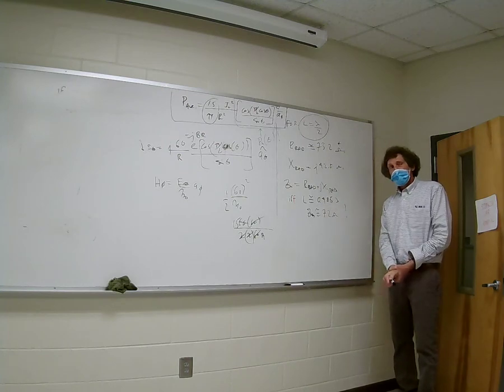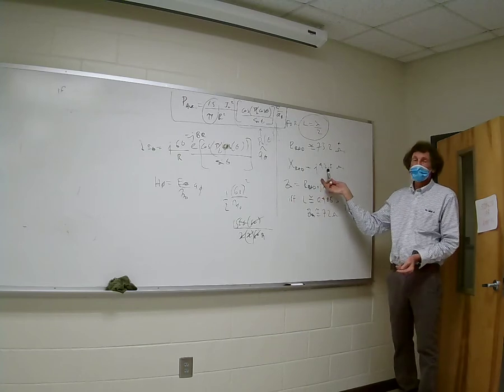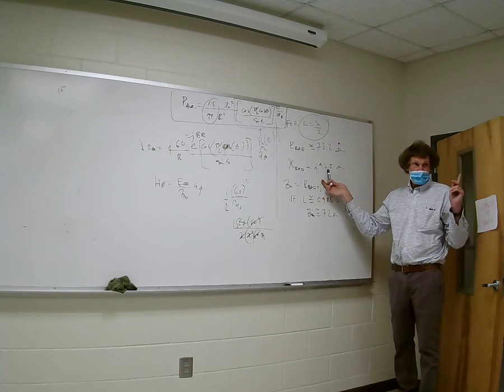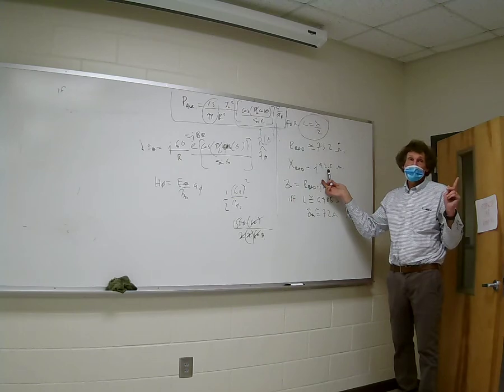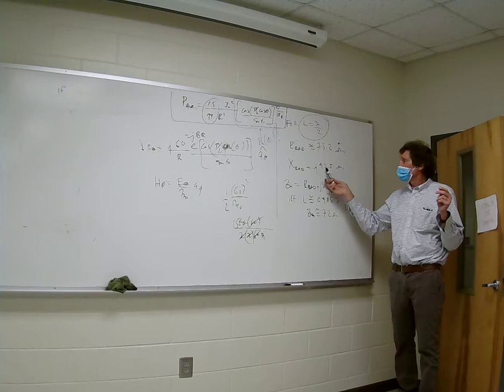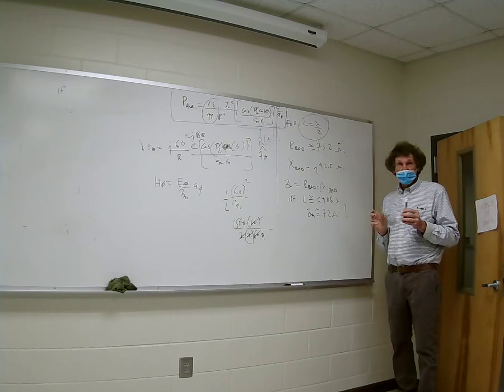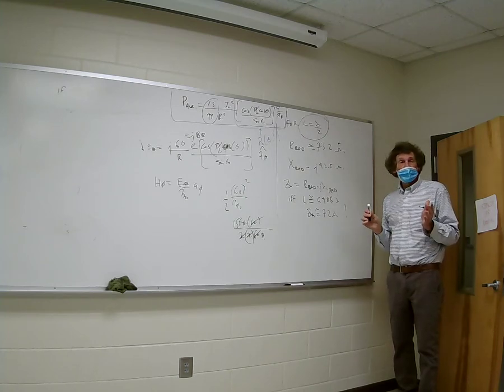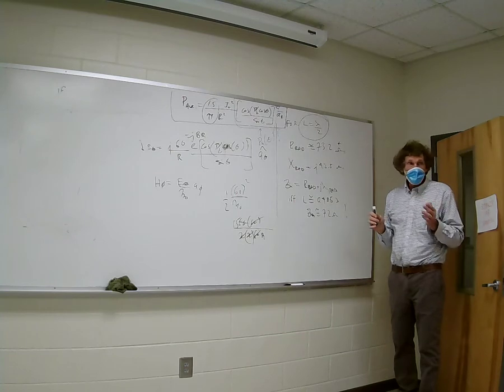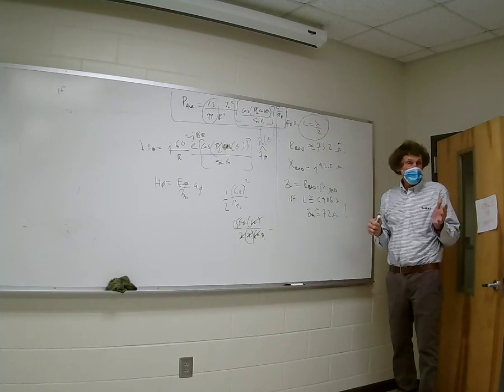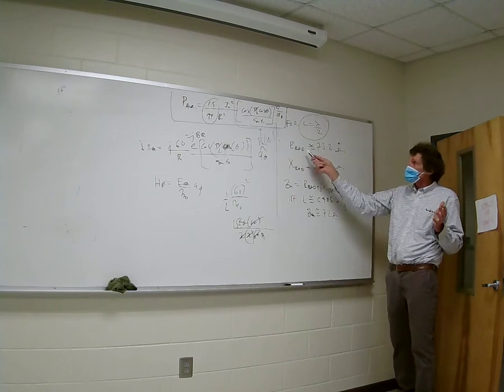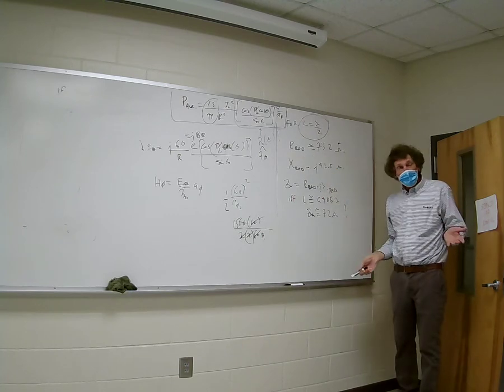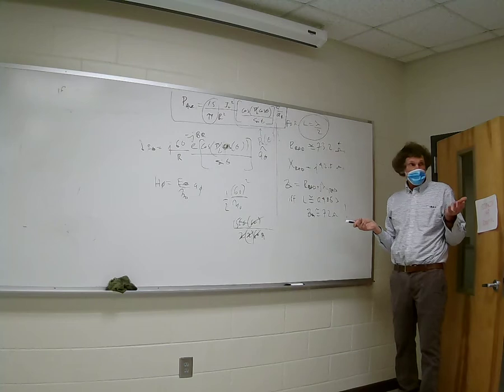The reason they do is you get rid of the reactance. See that j42.5 there? If it's exactly a half-wave dipole, you're going to have a reactance also. So you're going to have 73.2 plus j42.5. Now that j42.5 doesn't radiate power. The only thing it does is limit current, right? So if you want a certain amount of power radiated, because the power radiated just comes from that radiation resistance, you have to increase the voltage, and that's at a cost.